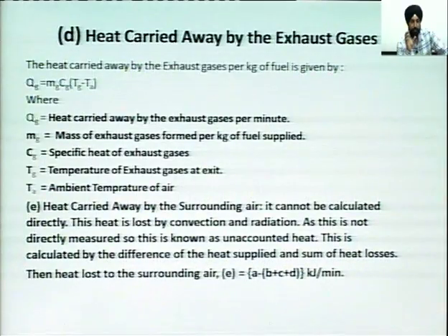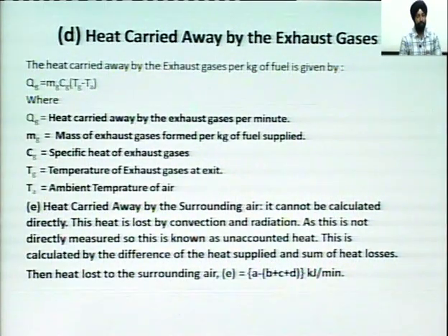This loss is difficult to measure directly. What we do is take the total amount of heat supplied to the engine and subtract all the other parameters, that is, the heat carried away by the cooling water, the heat equivalent of useful work, and the heat carried away by the emission, from the heat supplied by burning 1 kg of fuel.